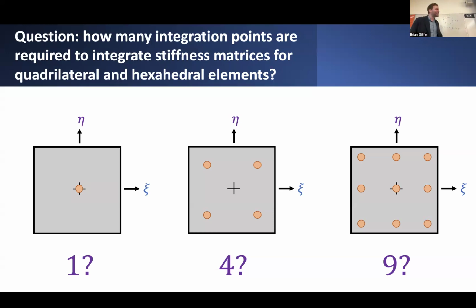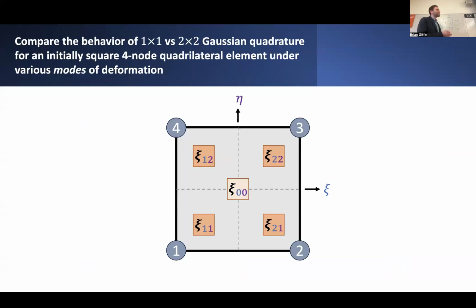And we'll have to determine what exactly we mean by something bad. All right. Well, suppose we took a different sampling of integration points, kind of borrowing from the idea of the 5-point integration formula. We'll do a sort of hybrid analysis where we compare a 1-by-1 integration formula, or just a single point integration formula, where there's only 1 integration point we'll put right in the center of the element.